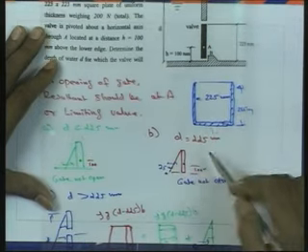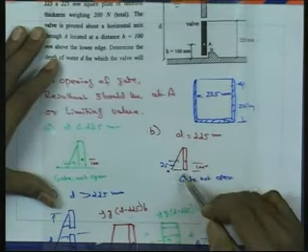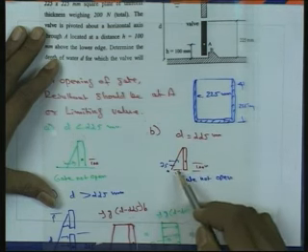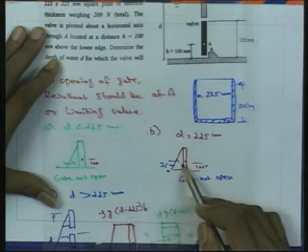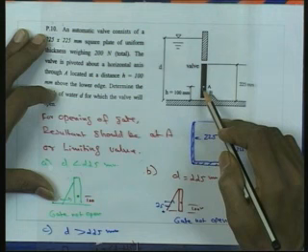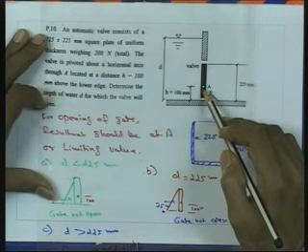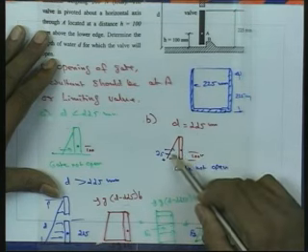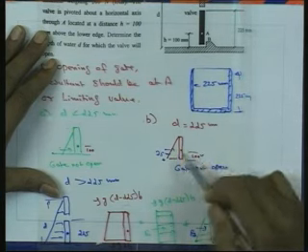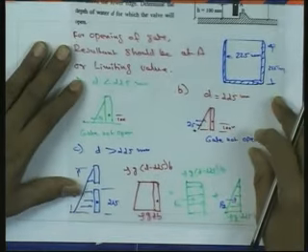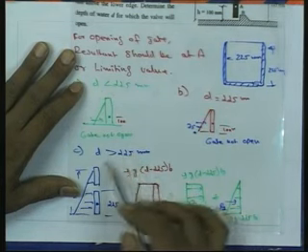So, for the limiting case it will be 225 by 3 from the bottom surface, which is 75 millimeter. So, this 75 millimeter is again less than the depth H where the pivot A is located. Since D by 3 is 75 millimeter, less than 100 millimeter, in this case also the gate will not open.